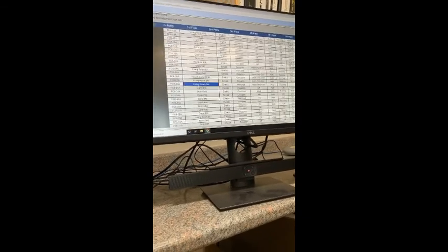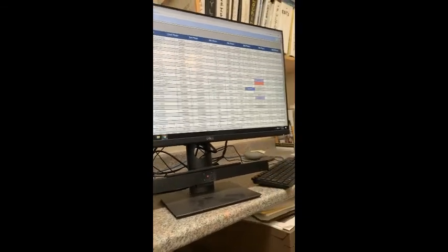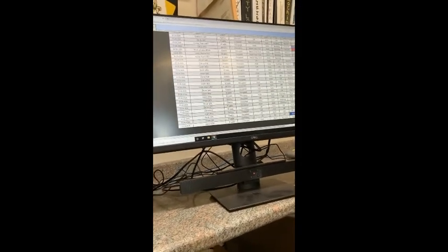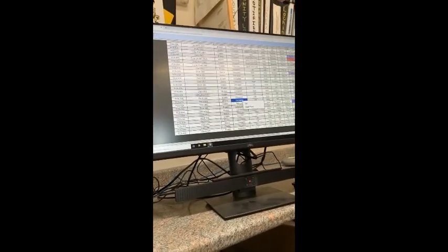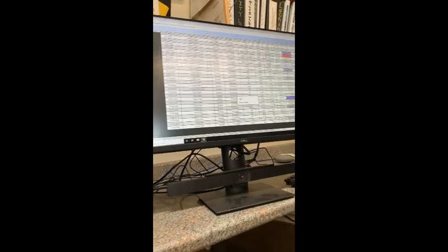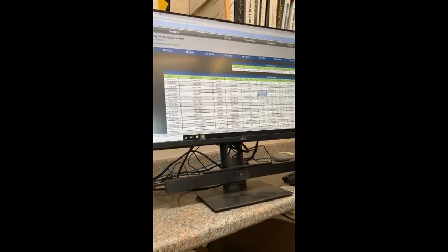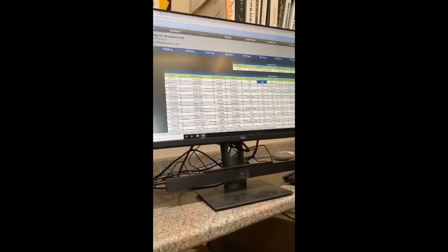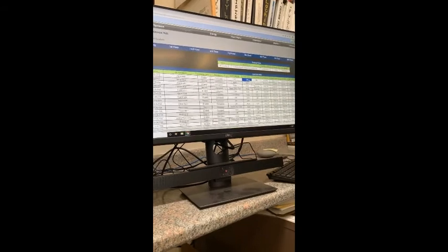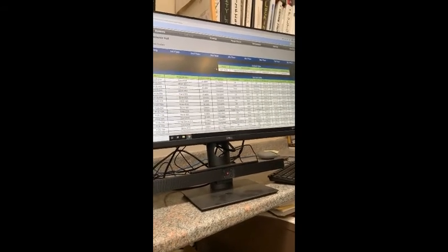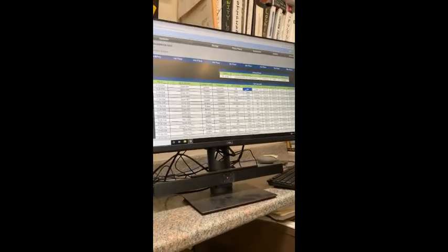You'll see some things like this living room here, where you won't see the set points because they're shared units. They all work off of one set point. Same thing, you'll see the temperature swings here. There are things that you can override and set, like the fan command. If it's set to off, that means someone's actually turned the knob to off and it would not come on. We can set that back to auto if we want.